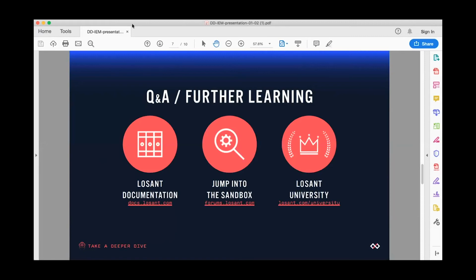Yeah, we really want to give everyone who works with Losant the flexibility to solve the problem the way that they need. So the answer generally to questions like this is yes and no. You are totally able to use a third-party broker within Losant. We have an MQTT integration that supports that, but we also have our own internal broker. As Adam mentioned, our primary method of communication is MQTT, so devices connect to Losant's broker and send data via Losant. So you have both options to do that.